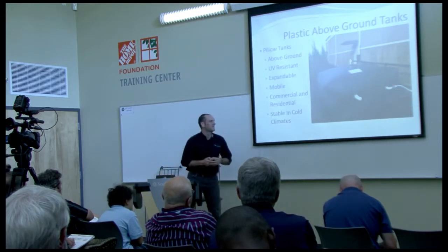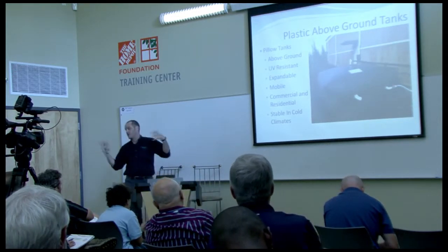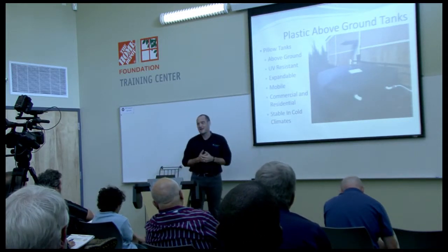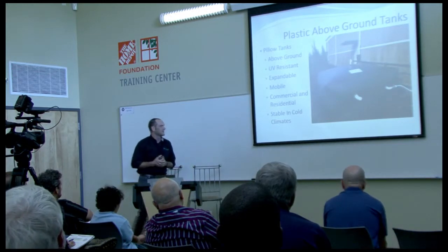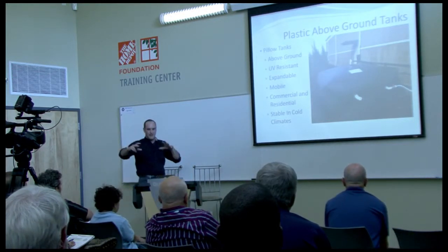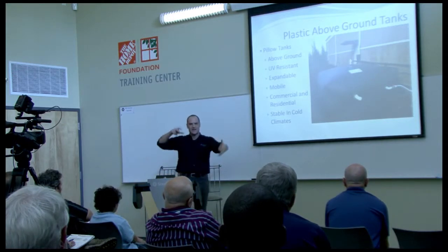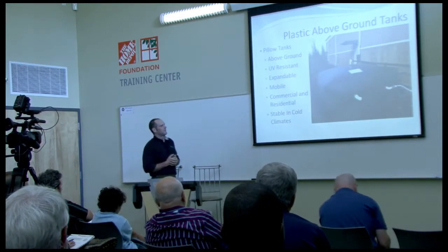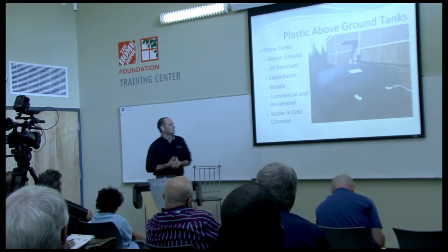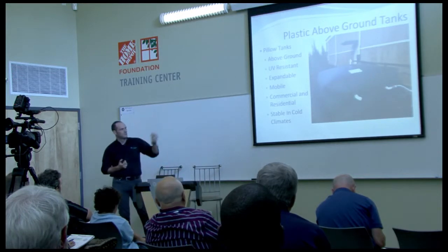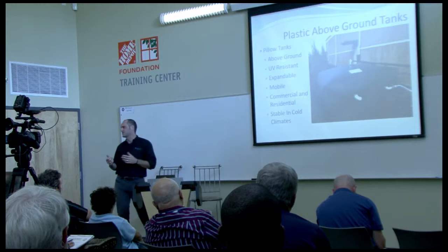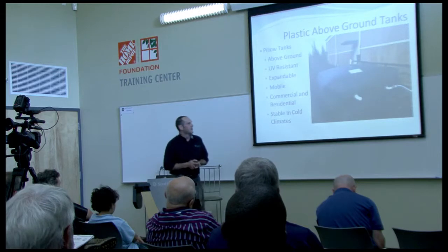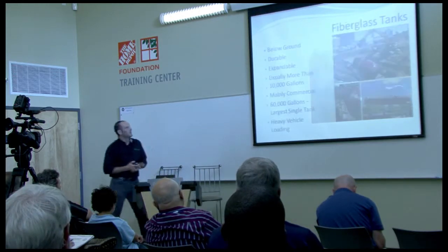I think there's many perceived advantages of them because they're easy. They're definitely not having the shipping issues you do with some of the larger tanks. If you ever want to move this tank, it would be very easy to move the tank. They're UV resistant. They're expandable as well. And again, if you have a specific area, you can customize the tank size because they can make custom sizes, and put it in for you. Great for if you're putting in crawl spaces, so it works well in residential applications. The actual liner is freeze resistant, and so you're not going to have issues with the tank cracking or anything like that during freeze. So another good above ground plastic tank system.